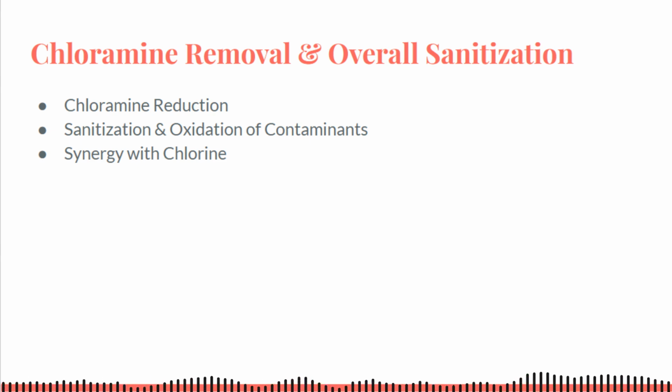Additionally, if a saltwater chlorine generator is used, an AOP system can extend the cell's life by reducing how hard it needs to work. Essentially, you get more chlorine output efficiency when an AOP or ozone system handles most oxidation. Important: neither ozone nor AOP produces a lasting sanitizer residual in the pool, so a minimum level of chlorine or bromine must be maintained in the water to continuously disinfect areas the circulation system may not reach.